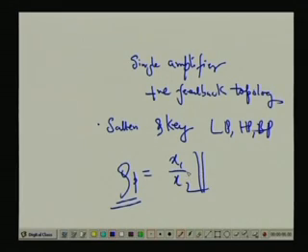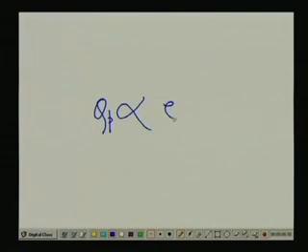This ratio is high only if I use a large element spread. That means in all the single amplifier structures, in positive feedback as well as in the simple negative feedback topology, in all the cases, low pass, high pass, band pass, as well as the multiple feedback negative feedback circuits without any positive feedback, you will find that QP is directly proportional to the element spread.